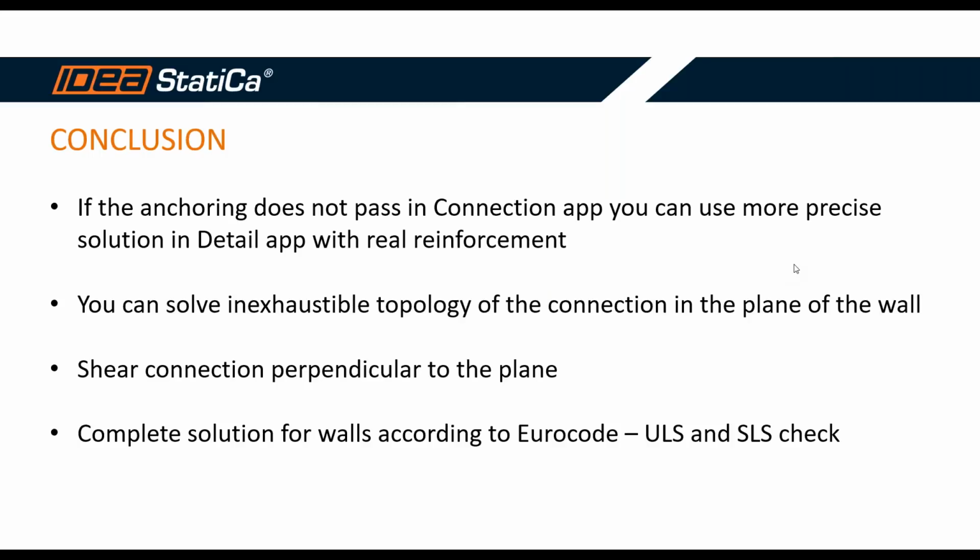An advantage of this application is that you can solve basically inexhaustible topology of the connection in the plane of the wall. You can even apply a shear connection which is perpendicular to the plane using the load that Lukáš showed you. It offers a complete solution for walls and complete code checks according to Eurocode, not only ultimate limit state, but also serviceability limit state checks, including crack widths.